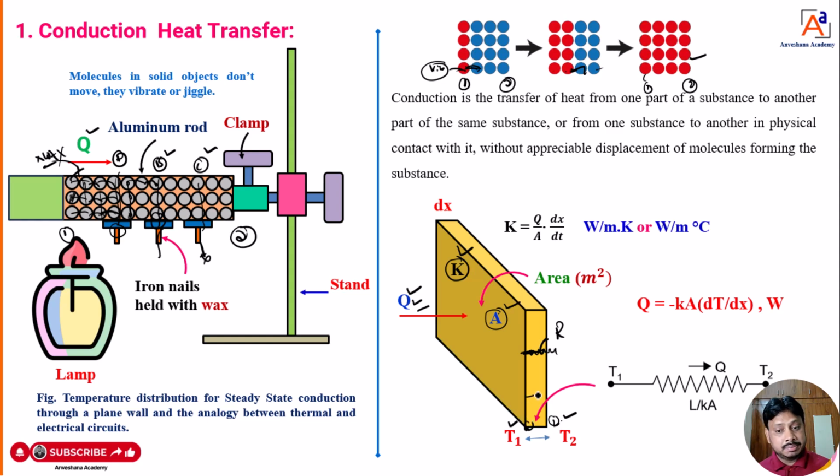When the heat is transferring in a plate, there is some resistance. That resistance is represented as R. All these temperatures and resistance I can show in a circuit. That is nothing but the thermal circuit, dear students. You can see here, the initial point is T1, the temperature of the metal plate at the high temperature region, because heat is moving in this direction. Then when heat is moving, there is some resistance. That resistance I can mark here as R. That R is nothing but L divided by KA, dear students. Then heat is moving. That movement of heat is represented as Q. Then it is going to reach point 2. That point 2 having a different temperature, I can mark here as T2.